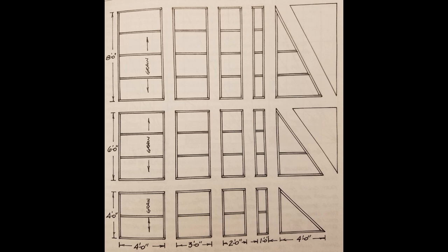Plywood can also be used to build your platforms. They can be substantially heavier due to the overall weight of plywood, but they can provide a pretty good and basic structure if you so need, or if some of the other materials aren't as readily available. While 2x4 is the most commonly used, we can also see 2x6s, which are a little bit wider than 2x4s. They create a bulkier and slightly heavier platform, but they tend to have a longer lifespan than your 2x4 frames.